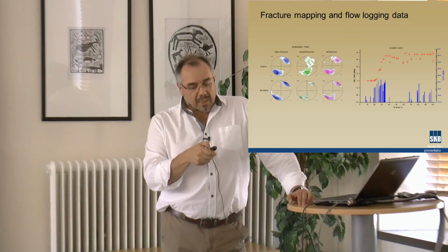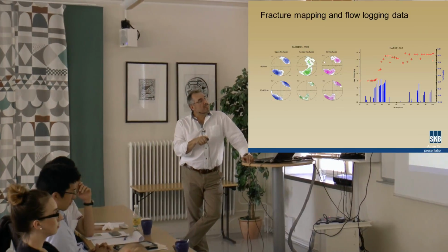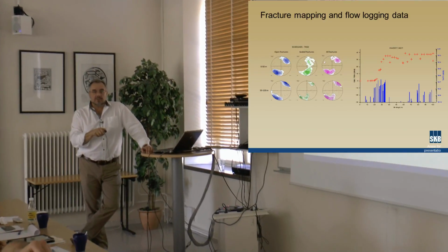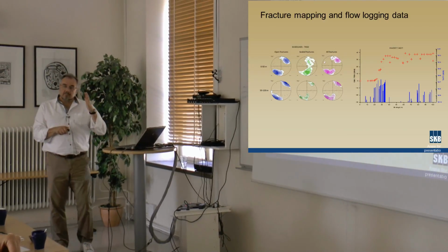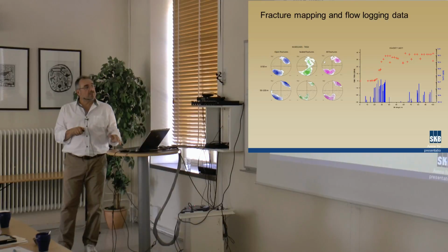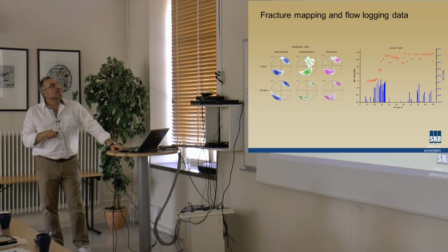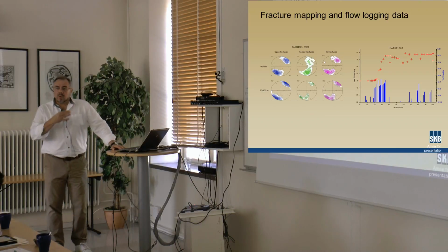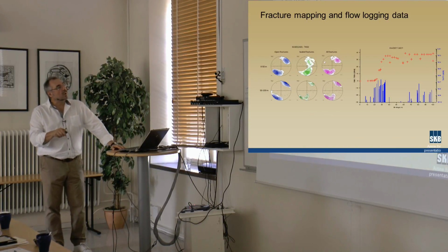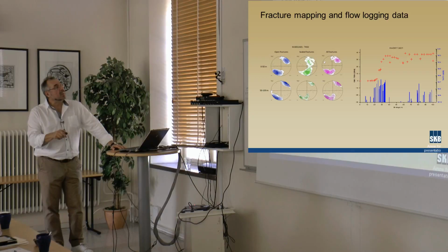And parallel to that, we measure the fracture geometries, that is, the direction and the inclination of them. And then we plot them in this type of stereo plots of different kinds to see how they are trending. So this is an example. Let's take this one, for example.